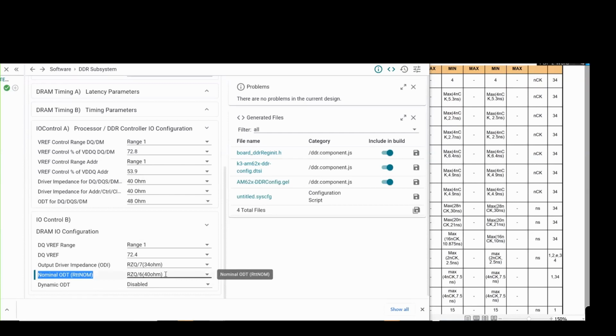So James, that's done on the board. How do we get the on-die termination resistance value? Isn't that supposed to be part of the data sheet kind of thing? No, this is part of board simulations. In this case, our drive impedance and termination are equal. I could get into what the I/O structures look like for DDR4.